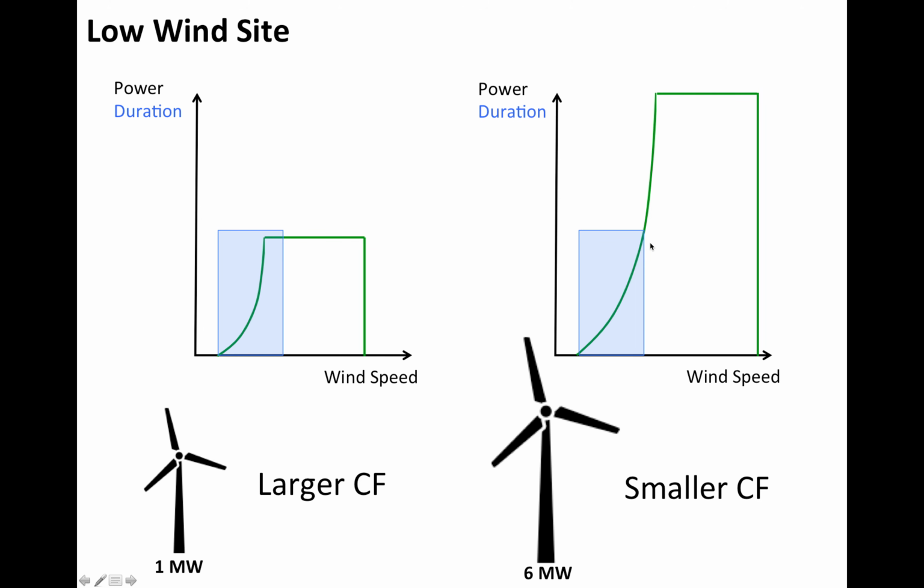The capacity factor is one of the most important numbers to consider when purchasing or selecting wind turbines for a specific site or specific wind characteristic. First, we don't want to buy a wind turbine that is too big for a given site. Bigger turbines have the capacity to generate more energy, but if it is too big for a given site, it's just a waste of money. So we are looking at a pretty low wind site.